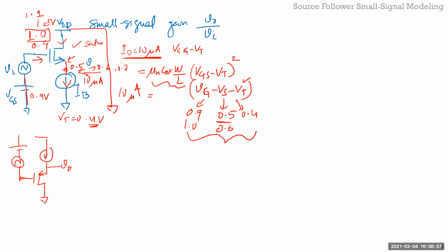So when we do op amps, you'll see that the first stage is a differential stage, which is like the common source amplifier. But then if you want to drive resistive loads, you have to follow up with a stage like this to provide the current. So one amplifies the voltage. The output stage makes sure that you can provide the current to the load. Okay, so that's why it's called a buffer.